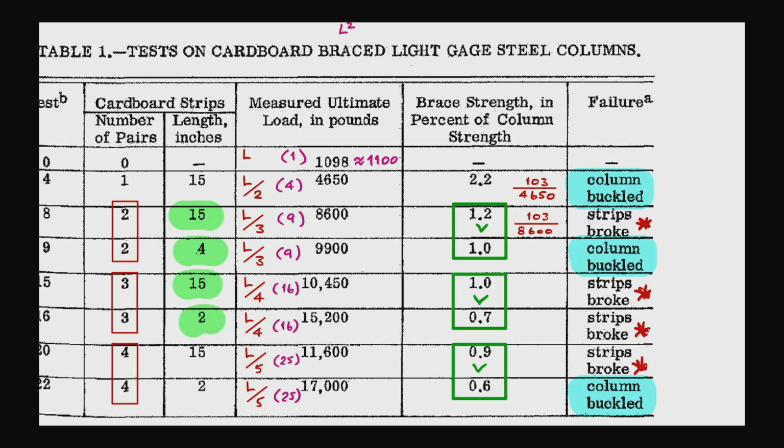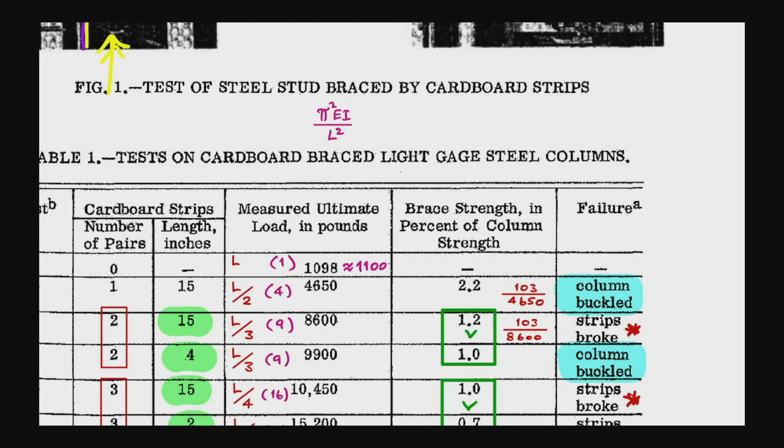Sometimes the force measurement at a low load like this, in comparison with a high load like there, your load cell at that time might not be a load cell, it might be just the pressure gauge reading. So the pressure gauge is calibrated with the proving ring in order to obtain the force magnitude.